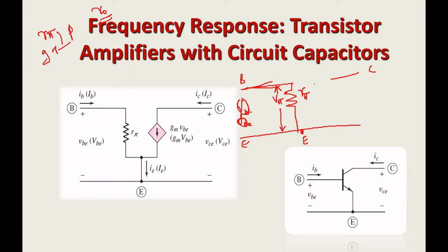The transistor is working in the active region because you are designing an amplifier. You know that in the active region your output current will be beta times IB. I already said that beta IB and gm V pi are the same. Another thing to understand is that VBE is nothing but V pi, so I can write VBE equal to V pi. Base-emitter is mathematically equivalent to pi.